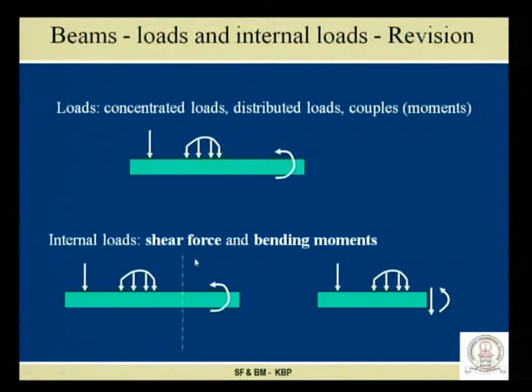Now if I cut my beam into 2 parts by section XX, this line shows a section, my beam will divide into a left part and a right part. Just visualize this left part purely. At that section, certain internal quantities will be developed. These internal quantities are referred to as shear force and bending moment, and our intention in this lecture is to determine these 2 internal quantities.